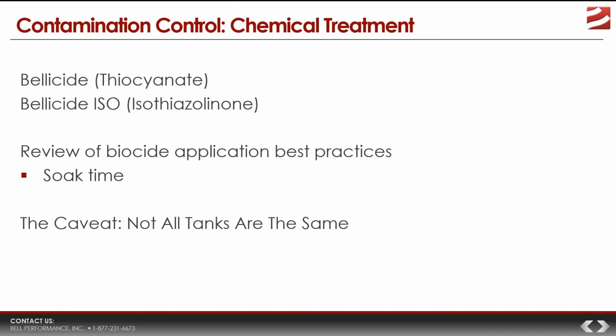So, what's the biggest thing that affects whether you're going to have multiple biocide applications? Biggest thing is the level of contamination. There are many tanks that may require 2 or even 3 applications. 3 is kind of rare, but it happens. How would you know if you have to reapply biocide? Only through ATP testing, only through condition monitoring after you apply the biocide. Only then could you actually determine if the microbial levels had actually been reduced to your desired level.